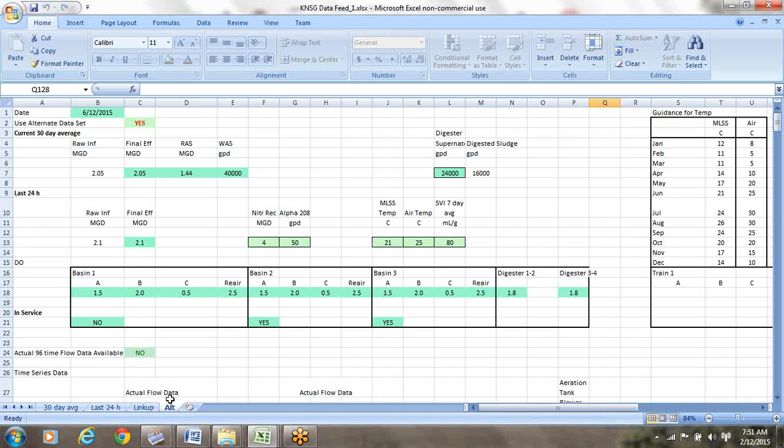Which again, when you get to age condition of equipment, it is a much more intelligent management of assets and processes, which is the key and one of the core IPs around IVops, that you look at assets and processes in combination. Because there isn't one plant out there in the world whose blower today, if it is 5 years old or 10 years old, is the same as the theoretical design blower capacity that the design engineer used. One of the blowers will have aged and it'll be different. So getting to real conditions and doing a retrofit from real conditions is very important if you want the design to reflect real conditions.